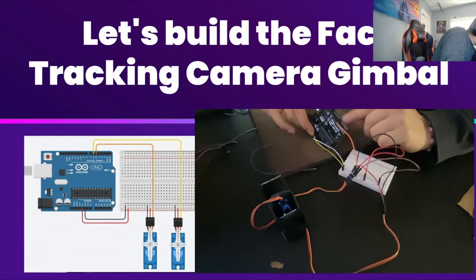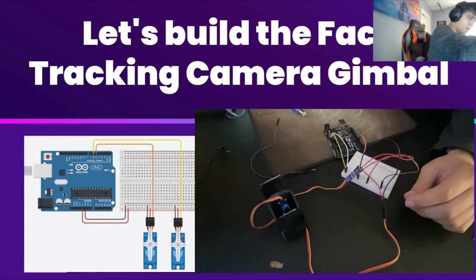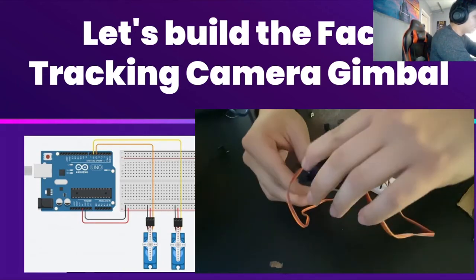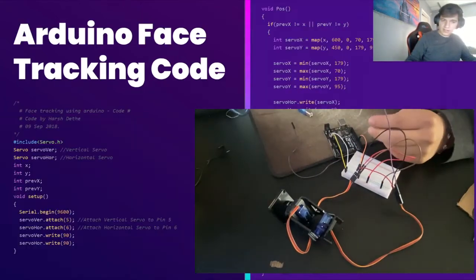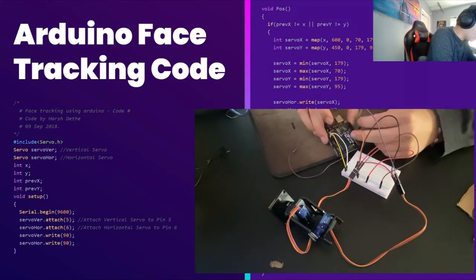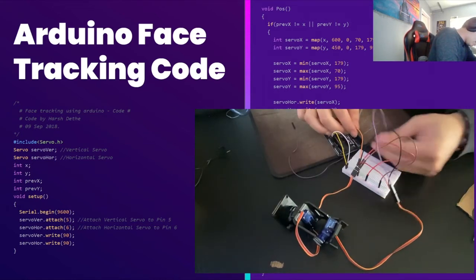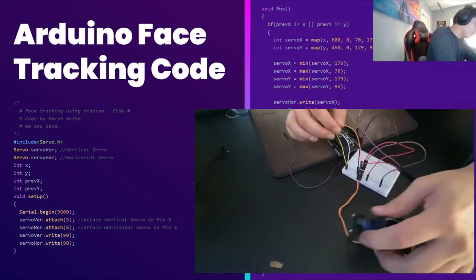Again, make sure that you can look on the side for the number and follow there. And then for the other servo, which is going to be the vertical one, that one is going to go into, let me check again, 5 is for vertical, 6 is for horizontal. So this is vertical, so this goes to the 5 pin, and then the horizontal one, 6 pin.